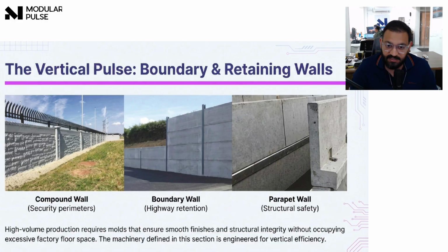In a precast factory, these walls are treated as standardized products. They are mostly cast vertically, which gives two big advantages. First, gravity helps the concrete compact naturally. And second, both faces of the wall get a uniform and smooth finish.